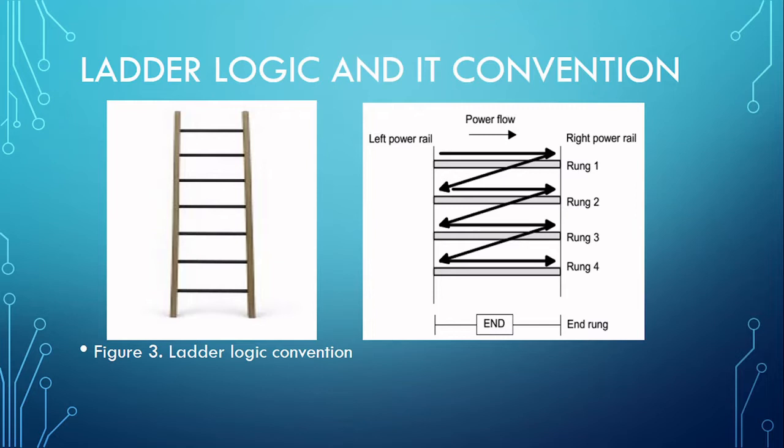So if a switch is normally open, it's shown as normally open on the ladder, or if a sensor is normally energized, such a sensor is clearly shown as such on the ladder diagram. Another thing to note here is that a particular device can appear repeatedly on several runs of the ladder, depending on what control operation is being done on such runs.